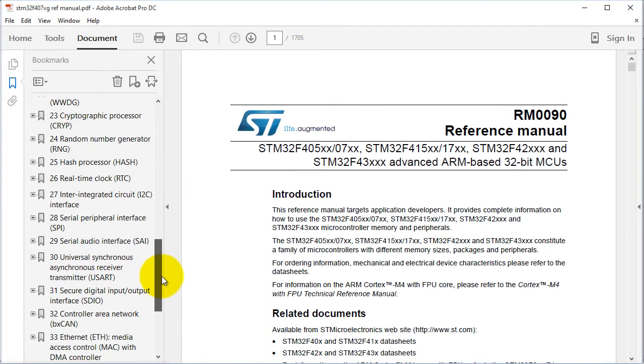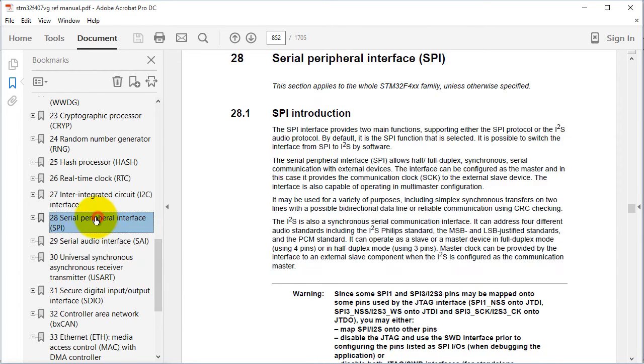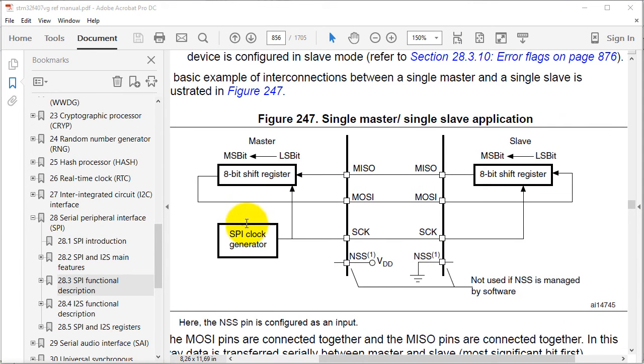Now let's see what is this SPI thing. It stands for Serial Peripheral Interface and is a very popular way for communication between devices, as it needs only a few wires and has a fair enough speed, up to several megabits per second. It uses two shift registers, one contained in the master unit and another contained in the slave. At the ticks of a common clock signal, serial clock, the information is shifted between these registers.